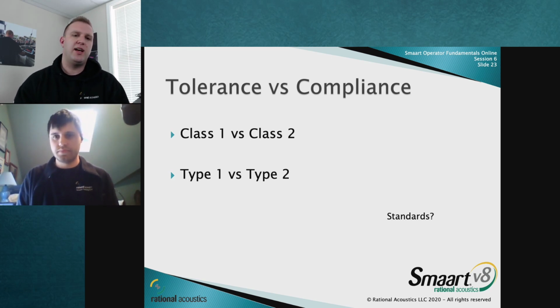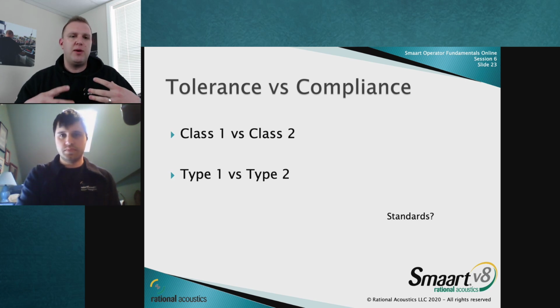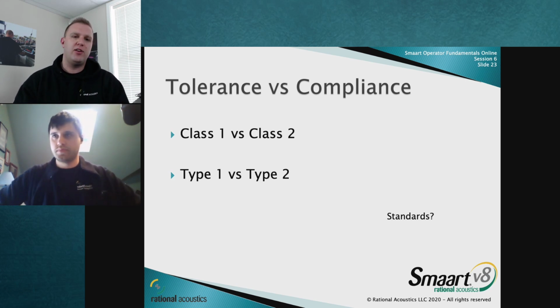Either they're class compliant or they meet class tolerance, and they're not necessarily compliant. In order for something to be class compliantly accurate, the entire measurement system has to be certified together, and you can't have user adjustable settings on that system like a gain knob. Because if it's too loud, you just turn down the gain, right? Well, that doesn't work for class compliance.